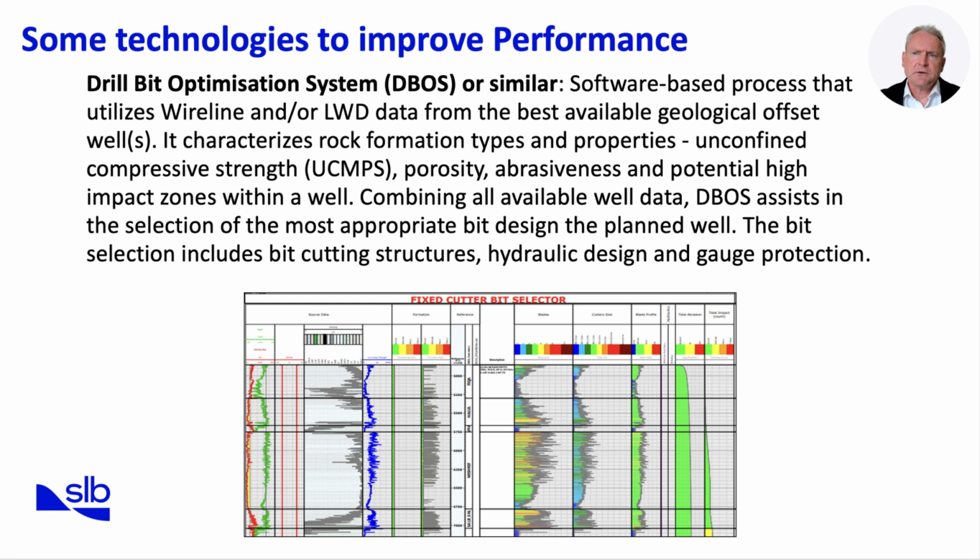By eliminating guesswork, DBOS reduces reliance on field trial and error, lowering overall bit costs and improving drilling performance. This approach demonstrates how data-driven software solutions can transform drilling outcomes, moving from reactive adjustments to proactive engineered planning. In the next slide, we'll expand this discussion by looking at dynamic modeling technologies that optimize the entire drill string, not just the bit.